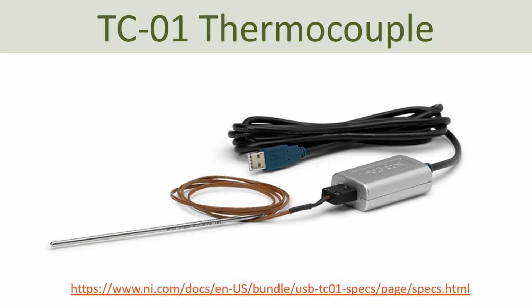I will just give a short overview of two different types, which are the devices that I have here in my office. The first one is the TC01 thermocouple. This is a simple DAQ device with only one channel, an analog input channel. And you can connect a thermocouple temperature probe, and then you can use that in LabVIEW in order to read temperature values from this thermocouple probe.